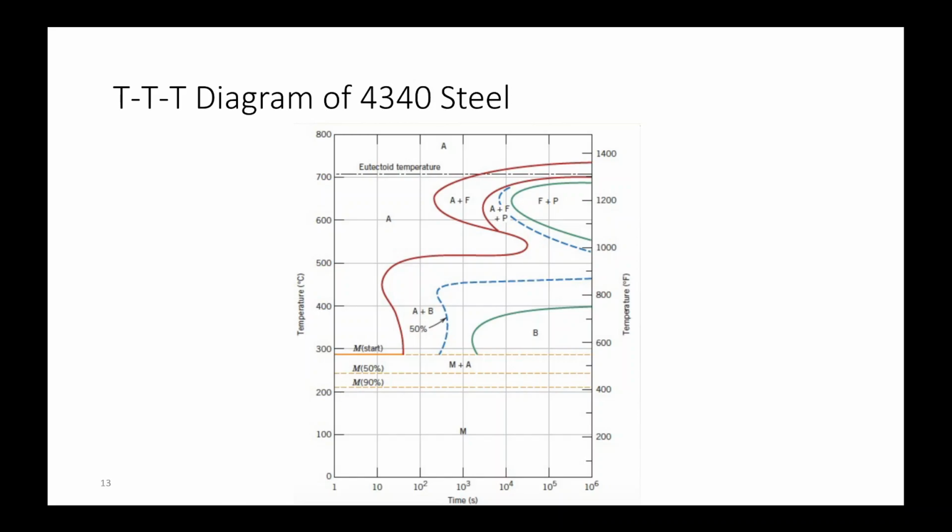No, in the case of Hume-Rothery, what you want is 100% solid solubility. For 100% solid solubility, it is mainly seen in substitutional solid solutions, for example the copper nickel system, right? There are other options as well, but in these cases you can see 100% solid solubility with an isomorphous type of structure.